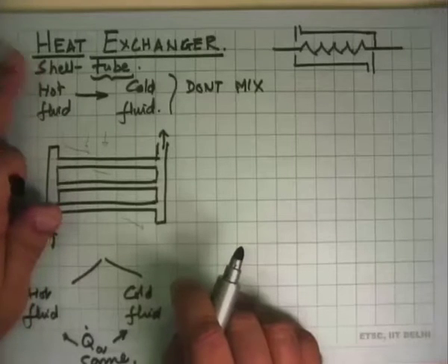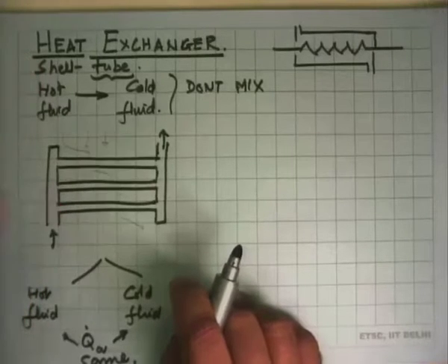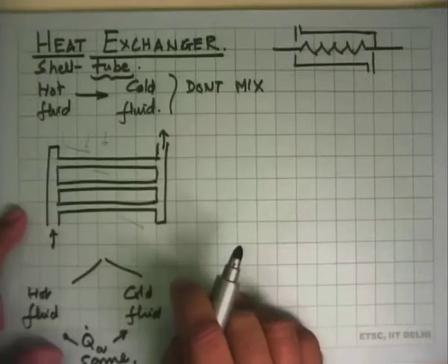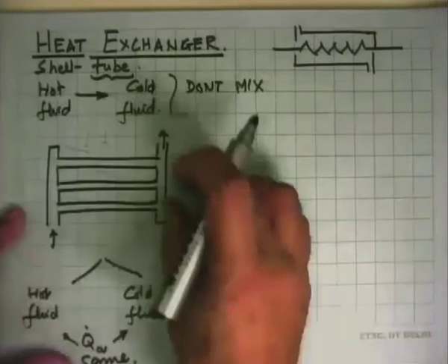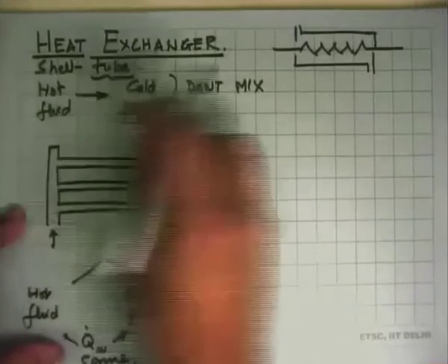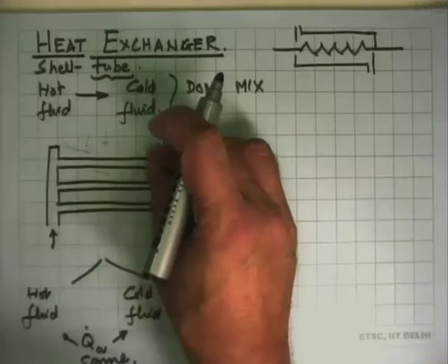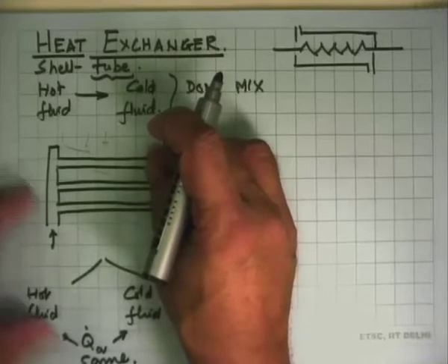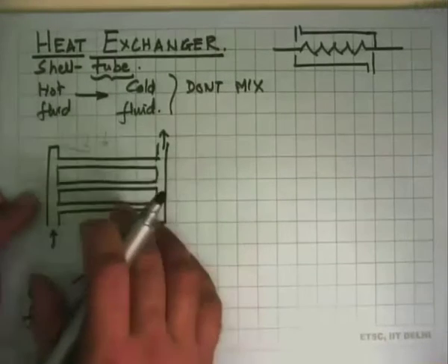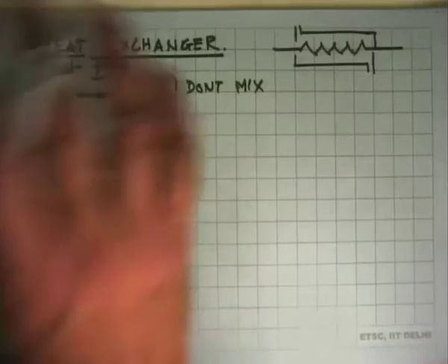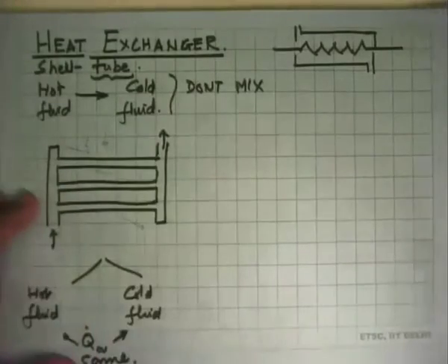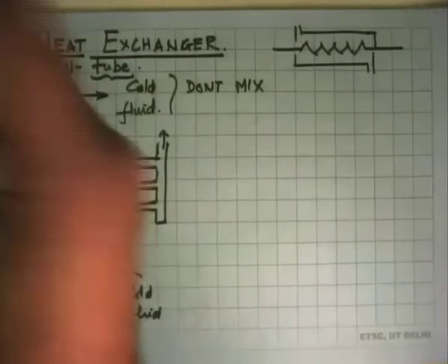Largely, you will see these devices being analyzed in a course in heat transfer, which is where you do the detailed engineering. If I want to have 1 kilowatt heat exchange between this fluid and that fluid, how big a tube should I have? What should be its length? What should be the velocity? All those considerations will come out of the heat transfer course knowledge. The thermodynamics knowledge tells you how much the pressure and temperature are going to be, no matter what the mechanical design or the thermal design of the heat exchanger.